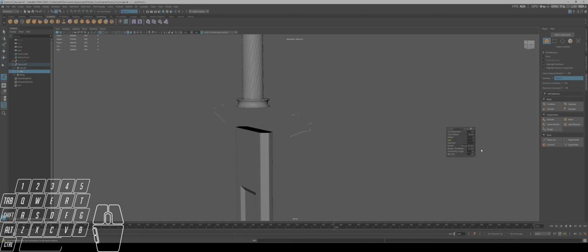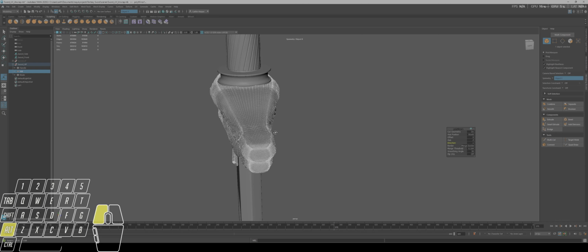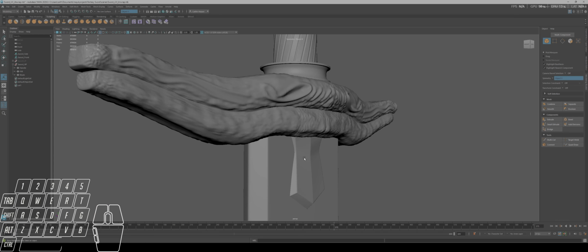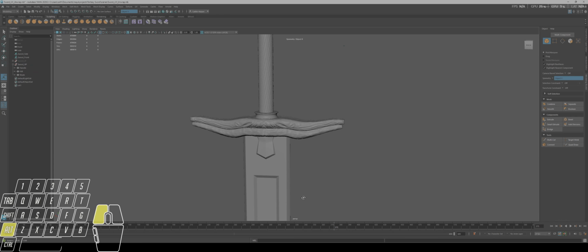So I'm just going to change my axis to Z and my direction to plus. And here's where it's taking a little bit of time as Maya calculates how to merge it all together and build it. It's not taken too much time that time, which is really good to see. If I just click off this, I've now got that consolidated model with the carved detail.